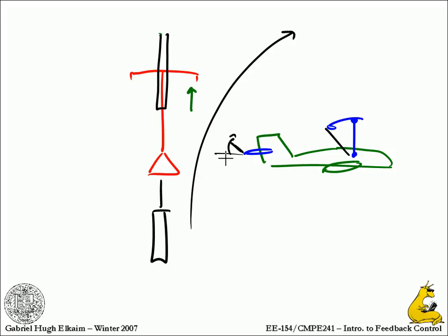Okay, so exactly. So when you pull the stick back, it causes the trailing edge of the elevator to go up, which generates lift down on the tail, which rotates the plane up, which causes a greater lift to appear on the wings, which will cause you to climb.